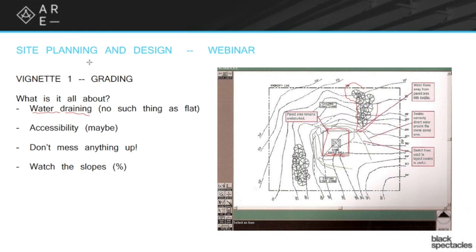100% slope is 100 feet horizontal compared to 100 feet vertical. So that's actually a 45-degree line. That's not a vertical line at all, right? So you think about that, let's say that's 100 feet horizontal, that's 100 feet vertical. That, drawn badly, is 100% slope. So you can very easily have a situation where you have 120% slopes or 140% slopes. They'd be very, very steep.